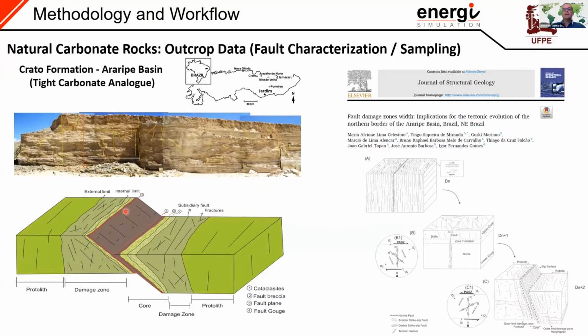They provide a structural map that characterizes the architectural elements of the fault, that is the core zones, damage zones, and fracturing in the damage zones, that in fact we are incorporating these features in our numerical model. So we are embedding our finite element mesh with these elements of the faults, discretizing each one of these elements and then upscaling. So this is the idea.